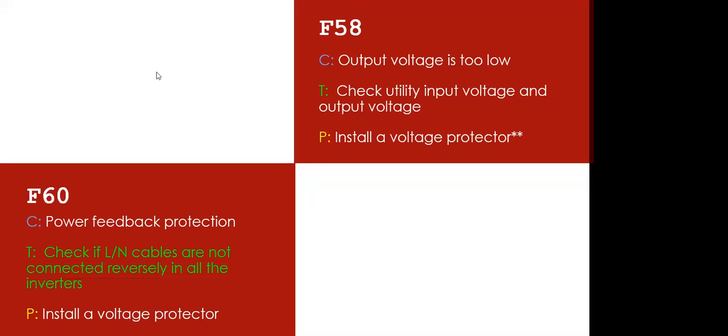It's not advisable to connect all the solar together and start taking source from the solar, either you use a bus bar or you use a breaker. It's not advisable for a high voltage inverter, but you can do that for the low voltage version of our inverter.